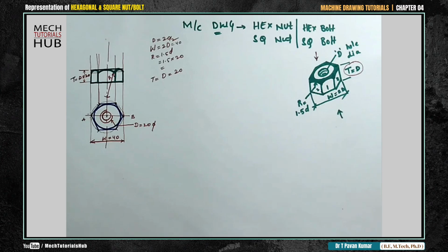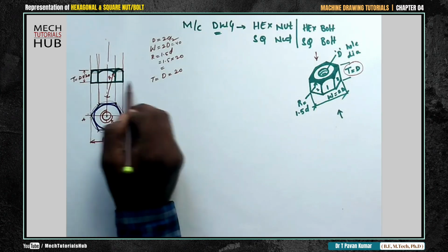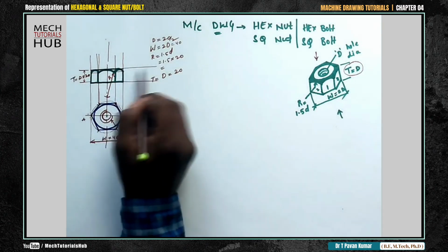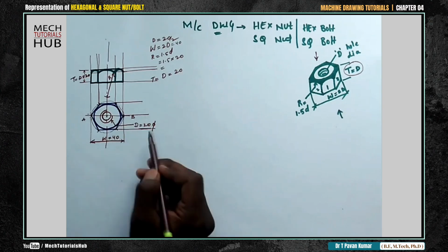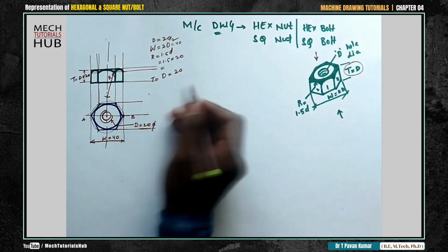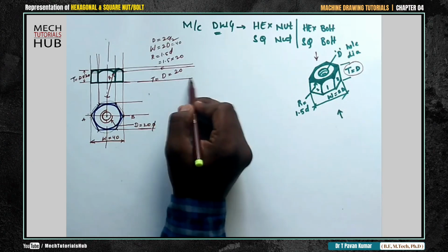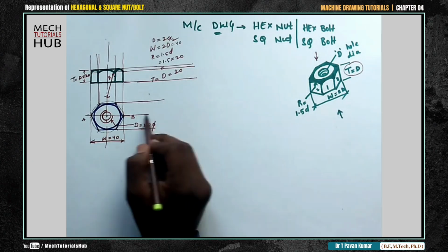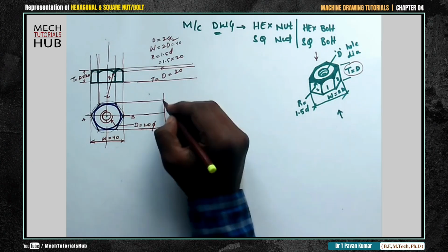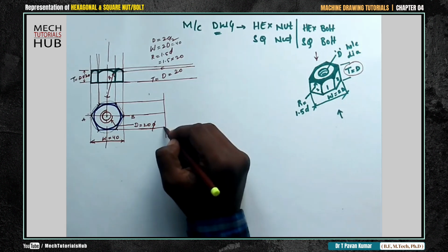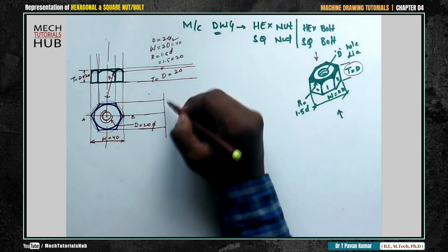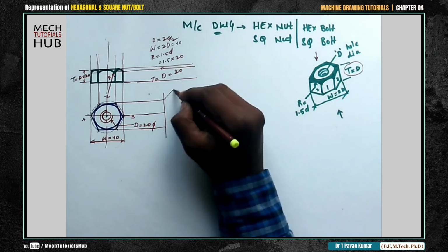Okay, they may ask you to draw the side view. If that is required, draw the projections of the front, and draw the projections of the top. Consider any; I don't have much space here, so I'll take an extension till this point. Then again I'll take these extensions also, and from this particular point align your drafter to 45 degrees inclination and draw this line.